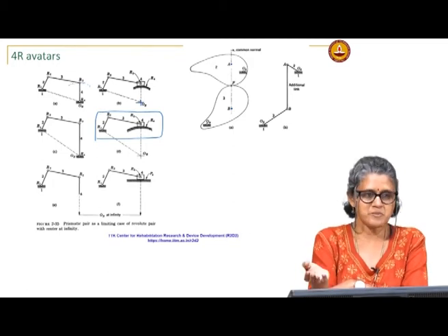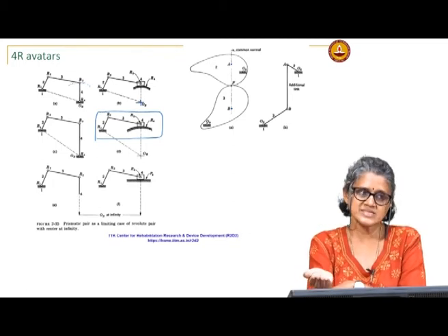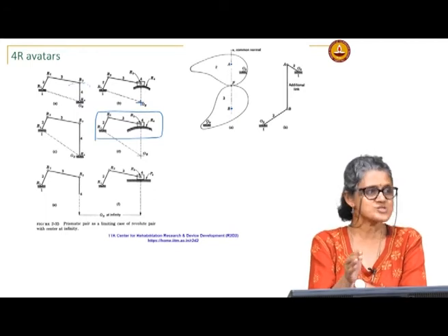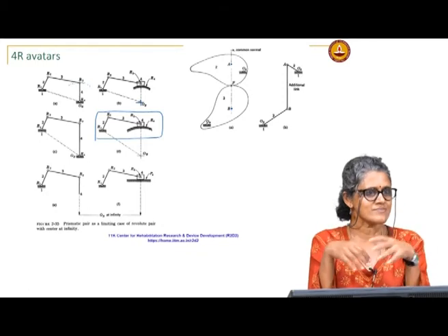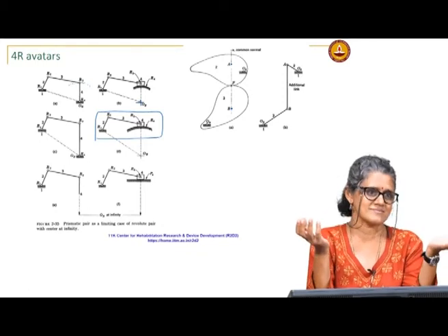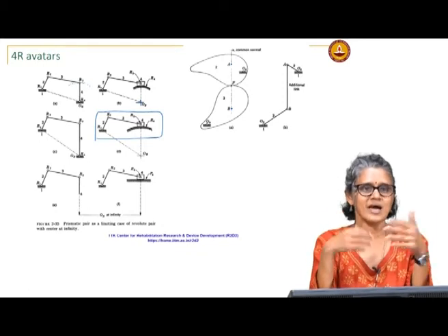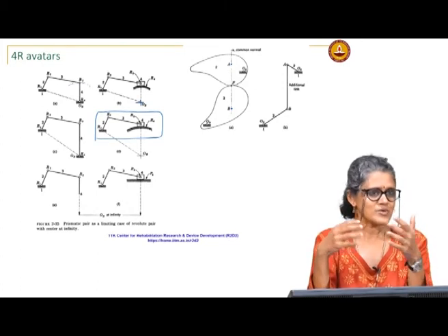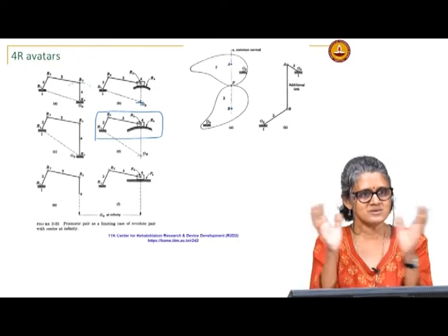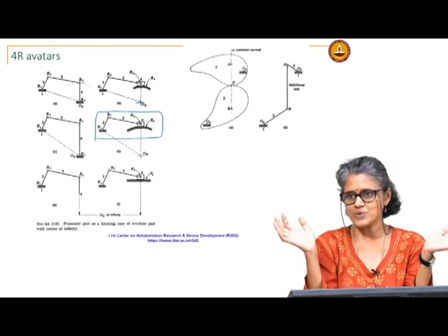The other side of the picture is what makes the cam follower system so versatile: it is essentially a series of changing 4 bars. With a 4 bar, once you have a set of links, what motion you get is what you get, right.